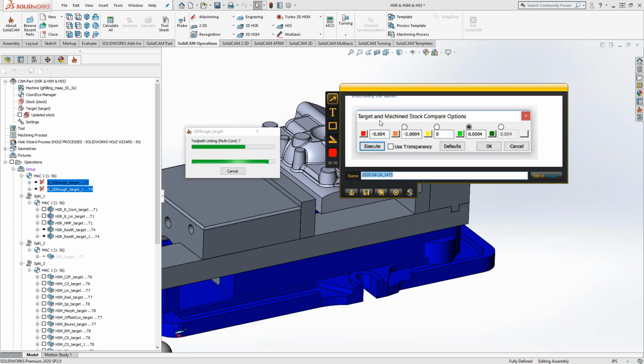So absolutely, it's a matter of the accuracy that you're looking for. It's like something that Kevin and I talked about earlier this week: if you need to keep to a certain tolerance, then just worry about that tolerance. If you make it too tight, then you're waiting for that STL to be built using that facet in the background, and it's going to take forever to build. Whereas if you really just care about a certain tolerance, then set that as your facet, and you'll be able to analyze to that level.